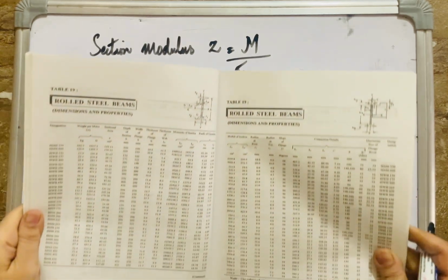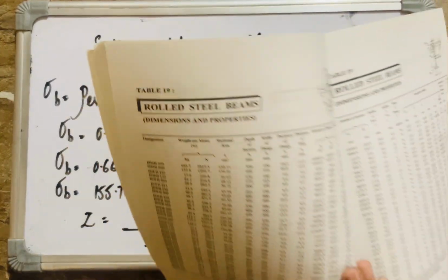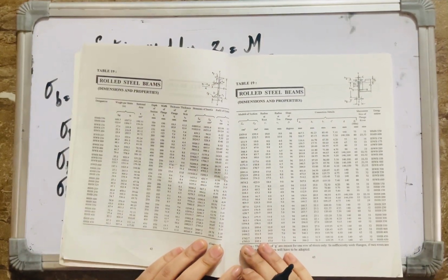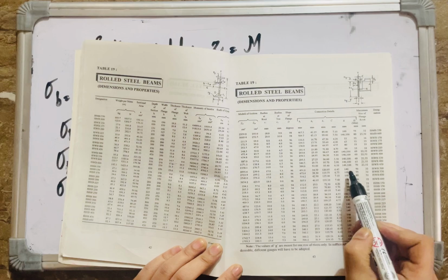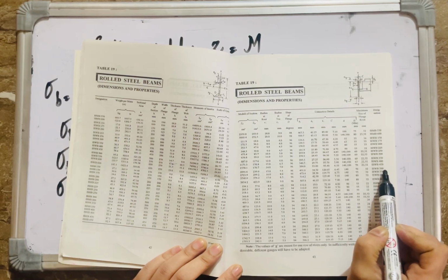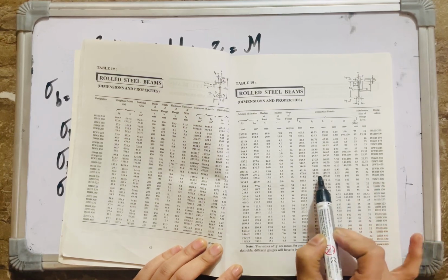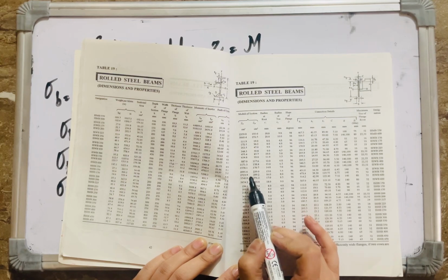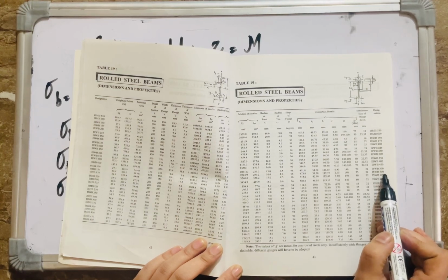And this is the steel table. This will give us information. How much is my section modulus? It is 2.63 into 10 raised to the power 6. So ISWB 500 will be insufficient. Let's check ISWB 550. ISWB 550 has a section modulus of 2.72 into 10 raised to the power 6 mm cube. So this will be sufficient and good enough for my stringer beam. So let's take ISWB 550, Indian Standard Wide Flange Beam 550.